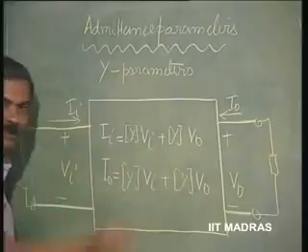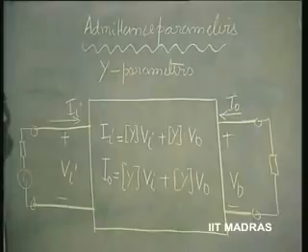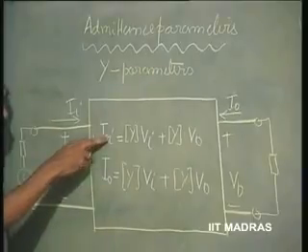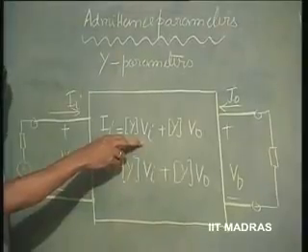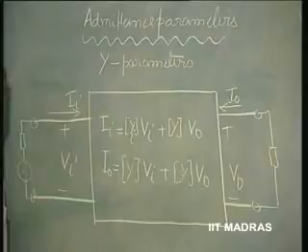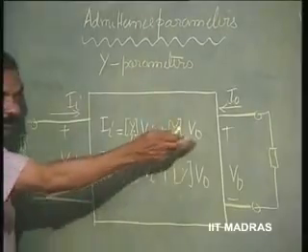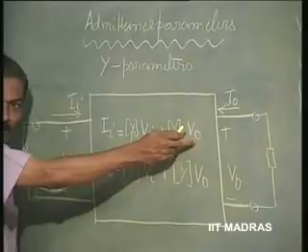These Y's have to be respectively defined now. All these are admittance parameters. Dimensionally they are admittances. So Ii related to Vi, again it is input, totally. That means Yi. And how does it get measured? When V0 is 0.